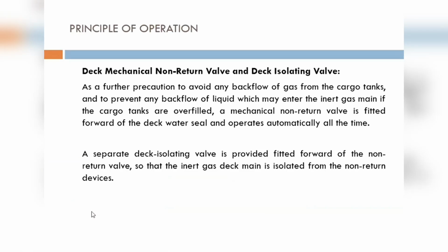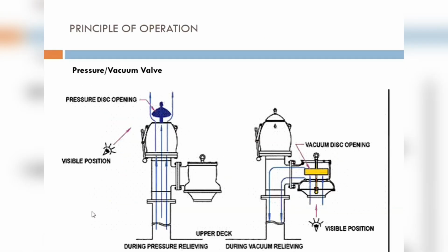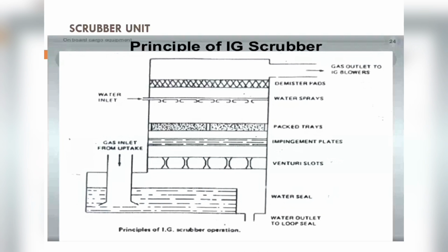So when you see that black smoke, black soot, black water coming when you go for a round, before you take over watch, this is one other thing you must check, whether there is water coming out. If it is too black, it's a good idea to tell the engine room it is coming very black, so they can adjust the air supply or increase the water pressure and reduce the soot which is going out to the overboard. And sometimes sound is also coming in pipes.